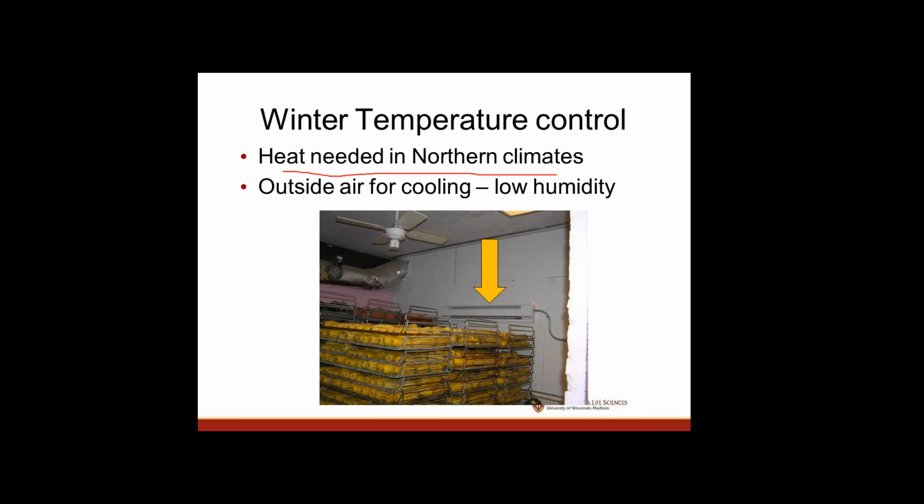So you can see in this facility here, we've got a heater on the wall, basically an electrical resistance heater, to add some heat into this squash storage room. Now, whenever we put heat in, we also need to do air mixing as well, so that we don't get stratification of the air. So that's important as well. One of the issues is, though, when we do heating, we'll have lower humidity, so we have to add humidity back into the room as well.